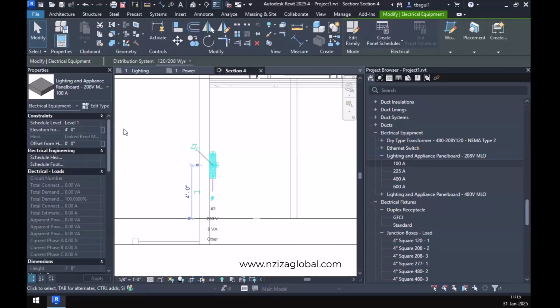In case there is some other requirement, if it needs to be above the ceiling, sometimes they tend to be above the ceiling because space is a restriction. If it is above the ceiling, please make sure that there is enough clearance, minimum 3 feet in front of that panel board for the electrician to actually work on that panel. Does that make sense? All right. Okay.